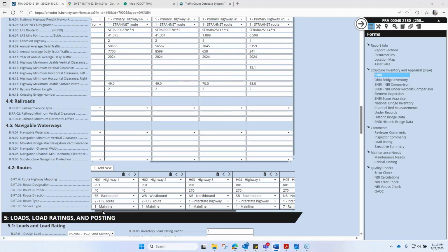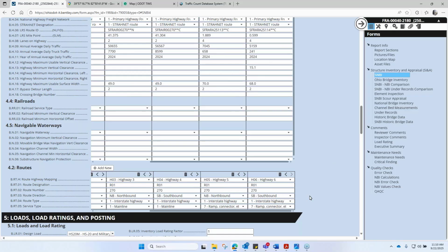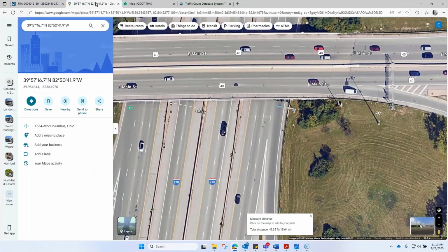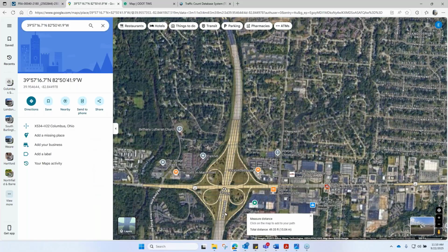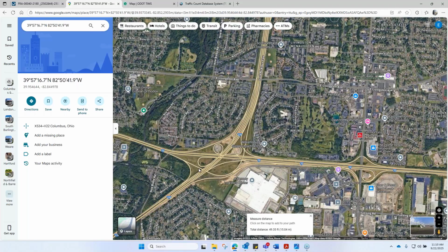So our routes, as I've said now, every highway feature gets one route assigned to it at minimum. You'll have cases where you have two, especially for ramps. Now in this case, these features are CD roads. So just one feature, one route is fine, the main route that's being collected and distributed. But if we had a more traditional ramp, such as this ramp right here, every time I need to put in this feature, I'm going to have two routes associated to it.